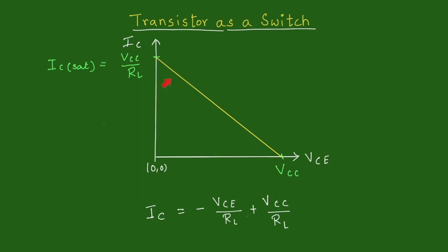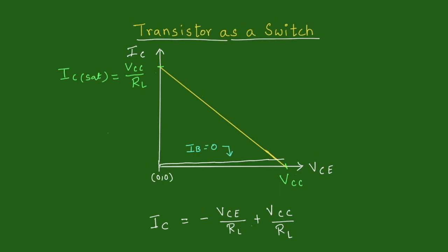The load line is a locus of the operating point of the transistor in the circuit. The operating point gives us the value of collector current and the corresponding value of collector to emitter voltage in the circuit. These values can be changed by changing the base current of the transistor. Thus, by changing the base current of the transistor, the operating point can be shifted along this load line. Now let us see the characteristic of this particular transistor when we change its base current.